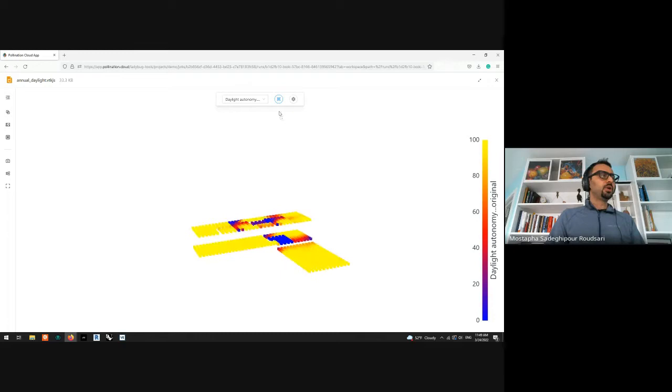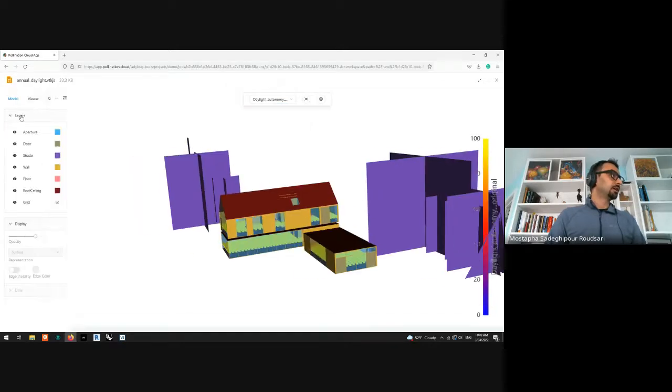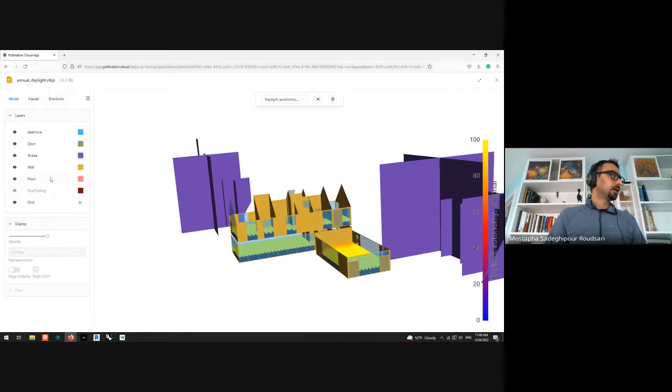We know that when you have multiple floors, right now we're not doing a great job. So we are adding a section cut, so you can basically see floor by floor if you want. But for now, what you can do, for example, in this case, is I can go here and again turn off roof, ceiling. I always have to select floors and make them white for better visualization.